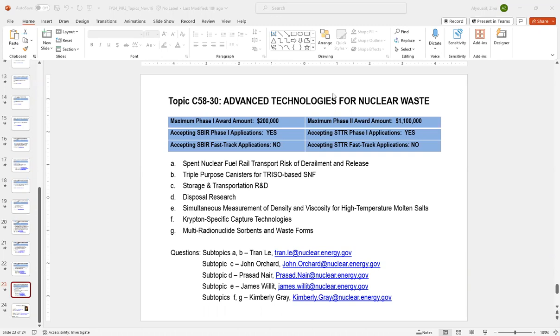measuring simultaneous viscosity and density measurements of molten salts, both on the benchtop as well as in situ in a molten salt reactor. We're going to emphasize, because the other topic area includes sensors for the benchtop, this one will be revised to be focused on in-reactor, either inline or at-line measurements of simultaneous measurements of density and viscosity, which will turn out to be very key properties of the fuel to make sure that it is staying within the qualification specs during reactor operation.